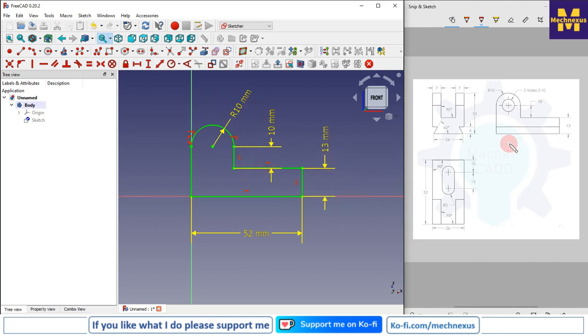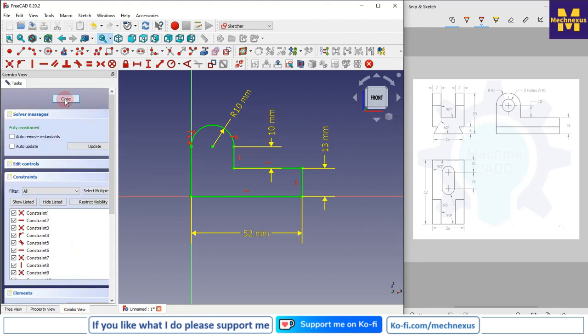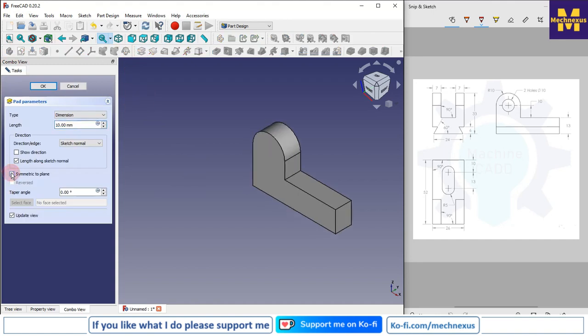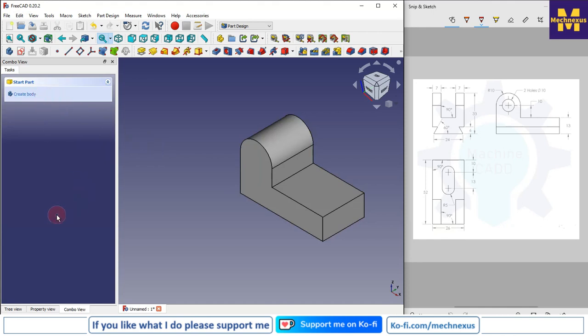Okay, and now we will find the width. So total width here it is given 26. So I will go to the combo view and close my sketch, and then I will click on the pad and I will click here on symmetric to the plane, and total width is 26, so I will give here 26. So this is the overall body we have made, and now we will make this cut.